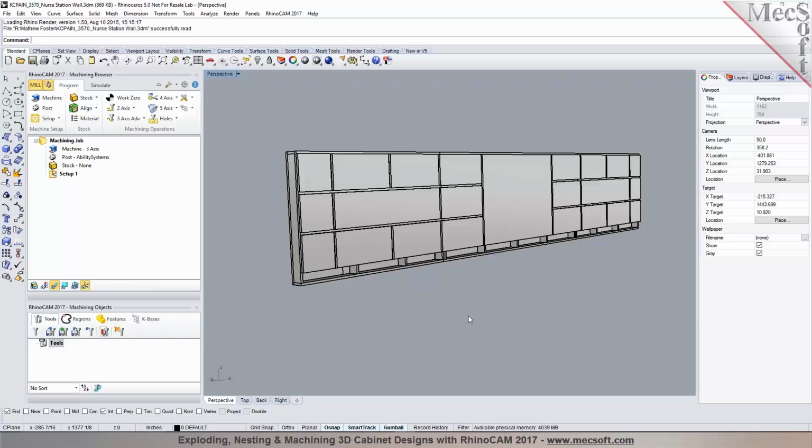But basically this would be the top plates and the bottom plates and the studs for the wall, the back panel, the front panels, and then all those removable panels. Okay, reveal panels is what we call them. So basically, they're all panels. They're all prismatic parts, or I would say flat parts. So we just have to break them apart and lay them out on a sheet and then process toolpaths on it. Is that right? Correct.